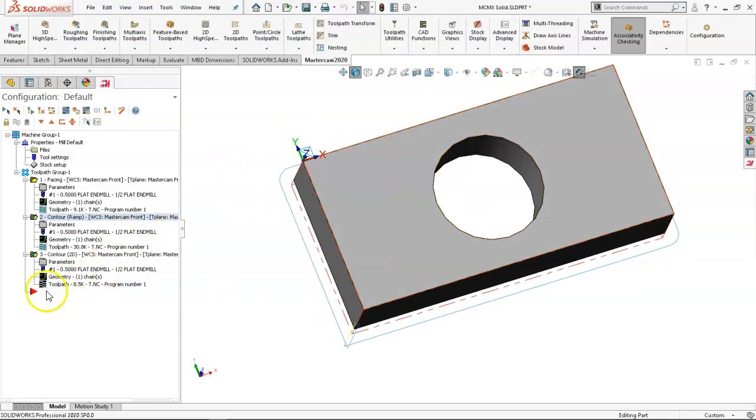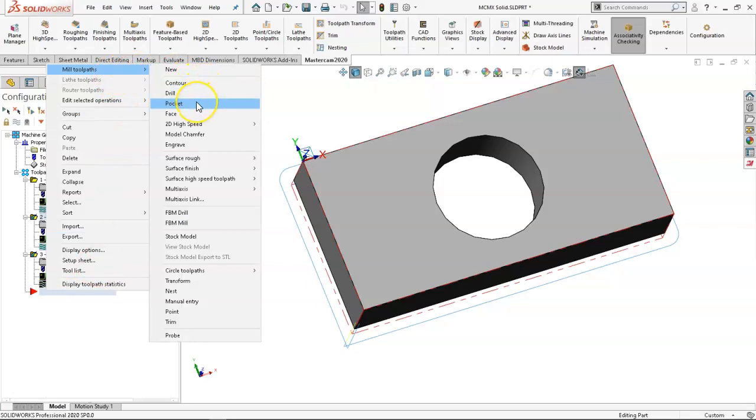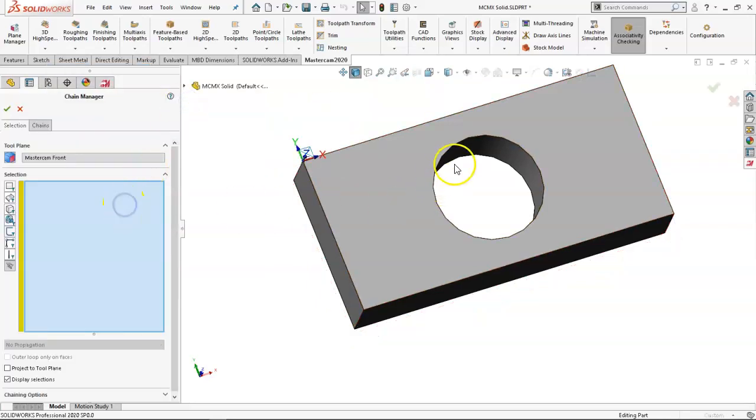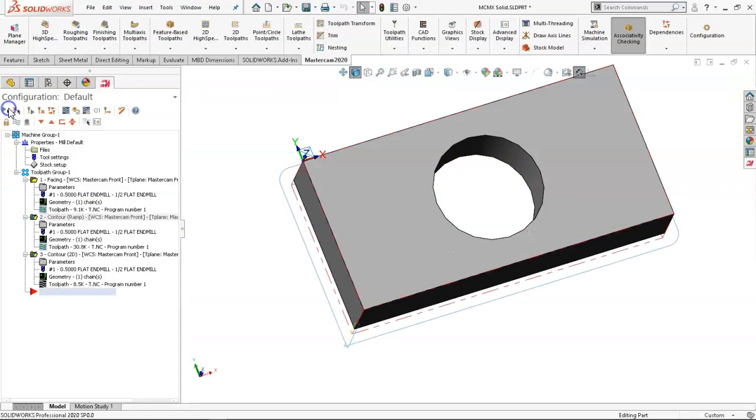All right, so at 2-inch, let's go ahead and run one of the pocket routines, or we could do the 2D high speed and have the dynamic mill go in and open it up. Let's just make it a pocket. We'll do one of the more traditional. All right, so we'll check the chain. When I highlight it, I should see the arrow in climb and with the correct side to cut.